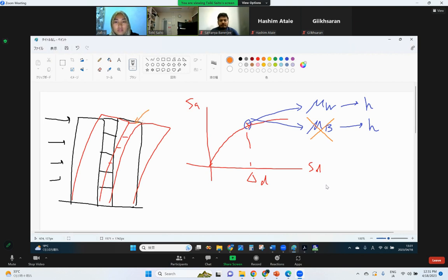Actually, for this viscous damper, damping force is a function of velocity. So in static analysis velocity is zero, right? So actually no damping force. So how do you get the damping factor at this target drift? This is a question, and you must think about it. Okay, Sensei.